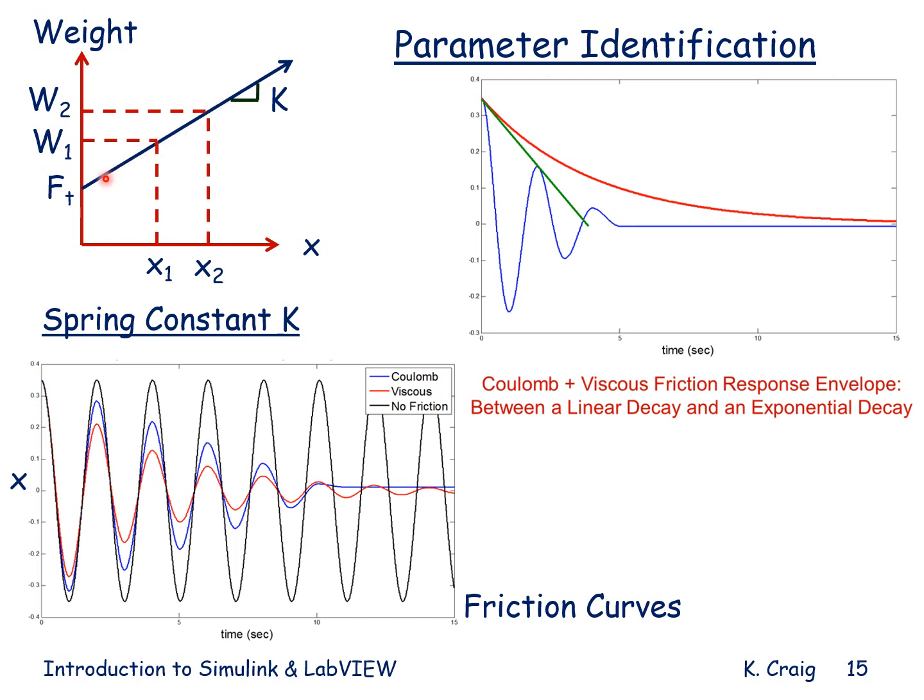If the straight line does not intersect the vertical axis at the origin, then where it intersects the vertical axis indicates what we call pretension, that in order to get the spring to stretch, to get the coils to separate, I need to apply a certain initial force before the spring will start to stretch. This is called my pretension, F sub t.